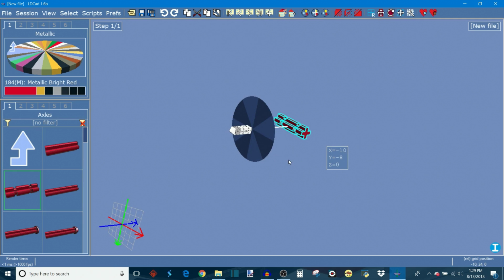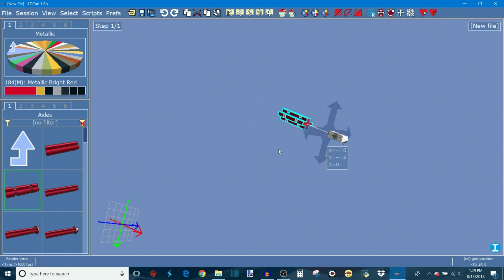So if you click on the M key, this is going to put the axle in move mode, and you can use the arrow keys to move it around, and this will allow you to move it in 2 dimensions. Next, you're going to want to learn the F, S, and T keys, and this moves the movement compass, which is what we're using to move the element around, to the 3 different axes that allow you to move your element in different dimensions. Now you saw before that we can only move it in these 2 different dimensions.